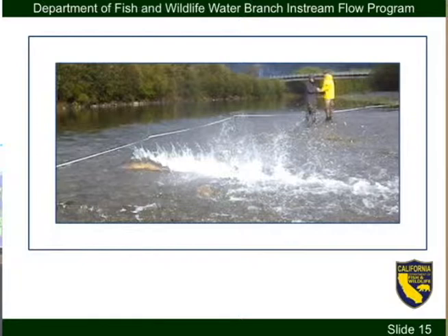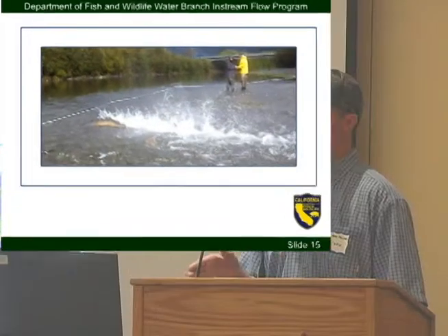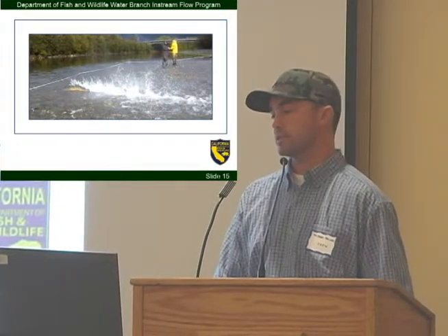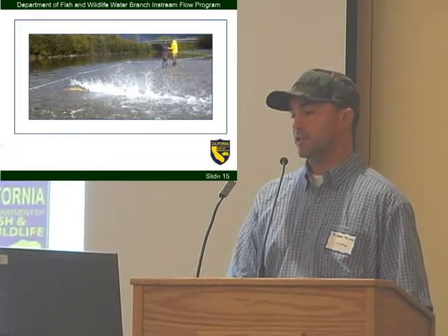This is lower than what this methodology would give you, and it's more of a belly scraping flow where this fish is about half out of the water moving through. I will also mention that the procedure I'm referencing here also gets used quite a bit for determining low flow fishing closures. At this flow right here, I believe it's 130 CFS, and the low flow closure is about 200. So it gives you an idea to be protective and to prevent anglers from being able to snag those fish as they come through these real depth sensitive sites. It makes a lot of sense.